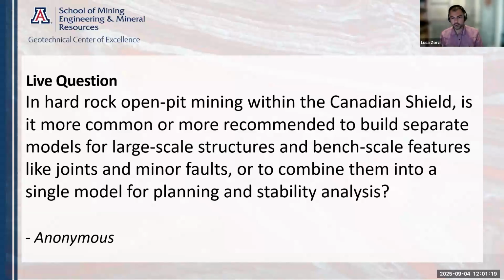If we're talking about joints that are easily picked out from the open pit exposures, or from data where you have continuous shear joints or joints that you can represent as a wireframe, then fine, they could be represented as such. But if the joint system has a direct impact on the slope stability, then we would combine the large-scale structural model and use DFN.